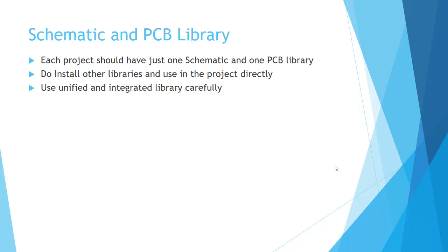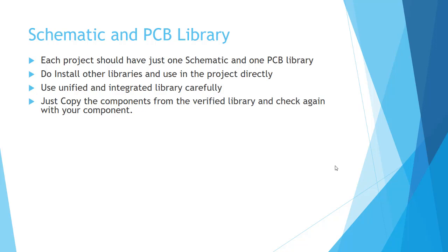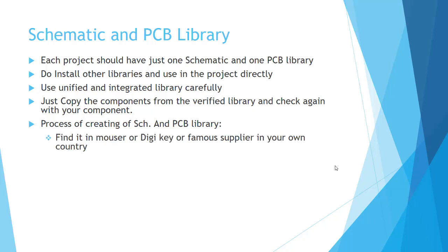Use unified and integrated libraries very carefully. Just copy the components from the verified library and check them again against your desired component. Creating the schematic and PCB libraries can be done in the following way. At first, find the component at Mouser, Digi-Key, or another famous supplier in your own country.